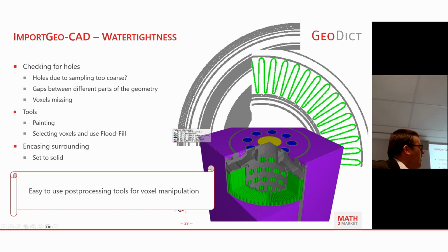Then there are also sometimes gaps between geometries, if the CAD structure in the CAD software was fine, but actually the surfaces didn't align properly. In one example, the casing wasn't stable enough, and it was easier for the flow to go through holes in the casing instead of through the filter element, which probably wasn't the intended outcome. So the next iteration of the CAD data was better then.